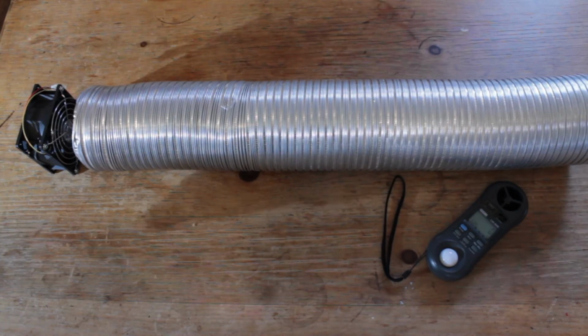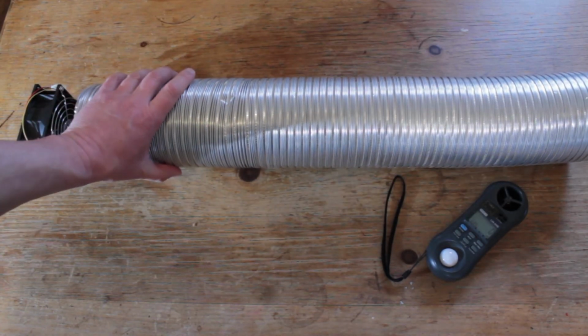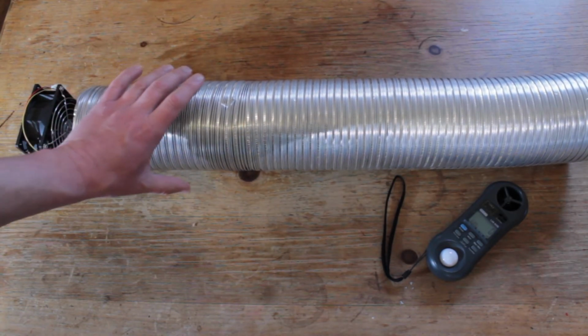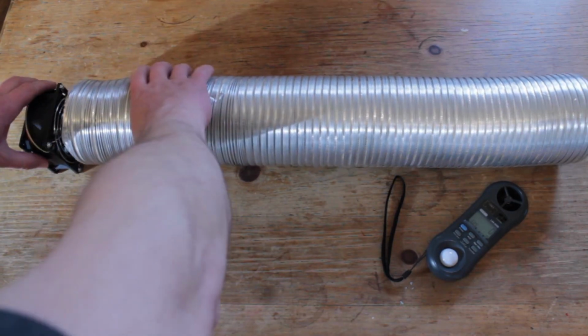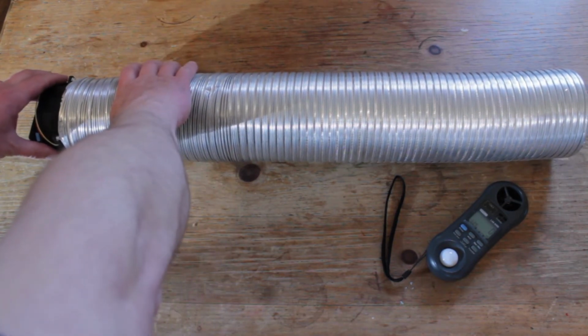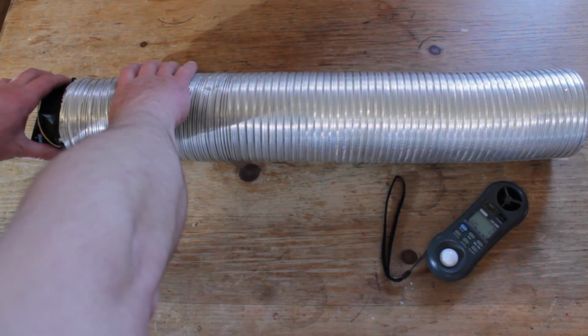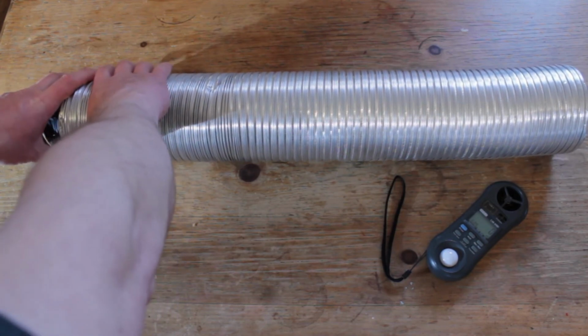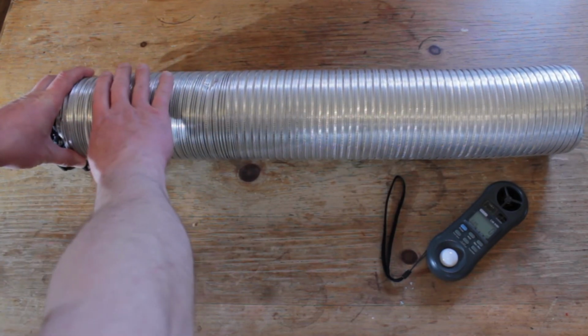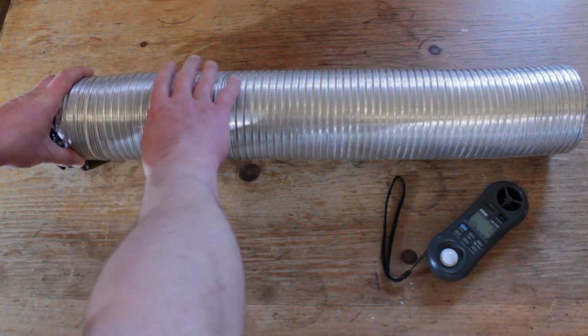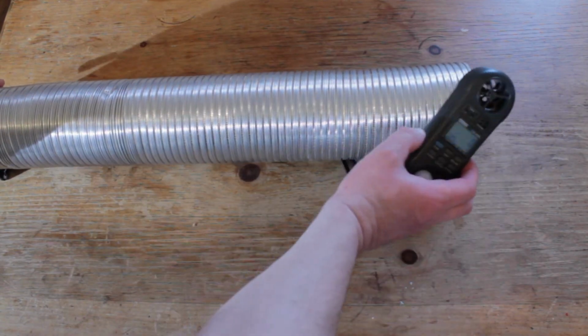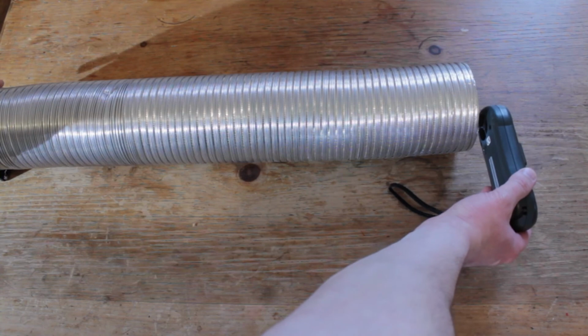To read the wind speed coming out of your heater, you're going to need at least a 2 foot long piece of ductwork, which you push up against the fan. The fan must be running at 100% maximum wind speed. Make sure that there are no leakages, so you have to push that right up against whatever enclosure you have on the fan. Then on the other end use your anemometer, but just on the edge.